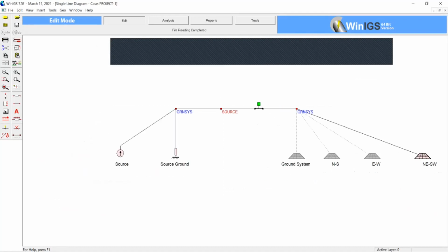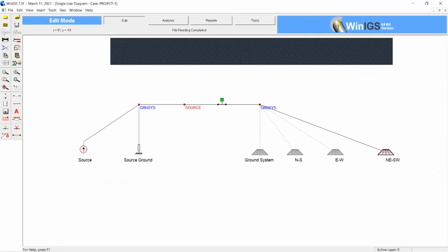So as per our discussion in the last lab class, I asked you to complete your grounding system by installing the ground conductor. Fans and ground rod you installed already, because it didn't take that long, but installing the grounding conductor was a bit time consuming. Then you have to make sure that the distance is 10 meters from conductor to conductor. So that was your homework. You should have done that.